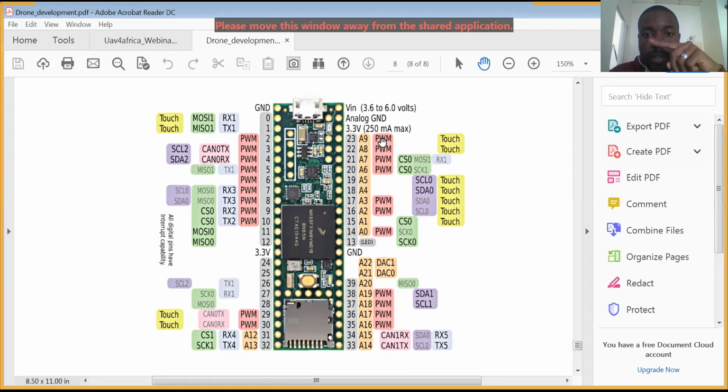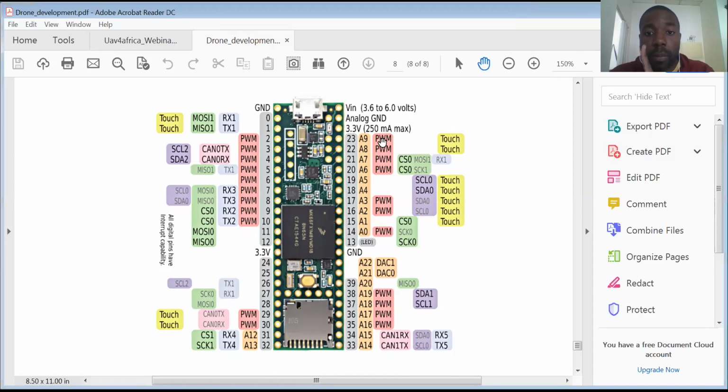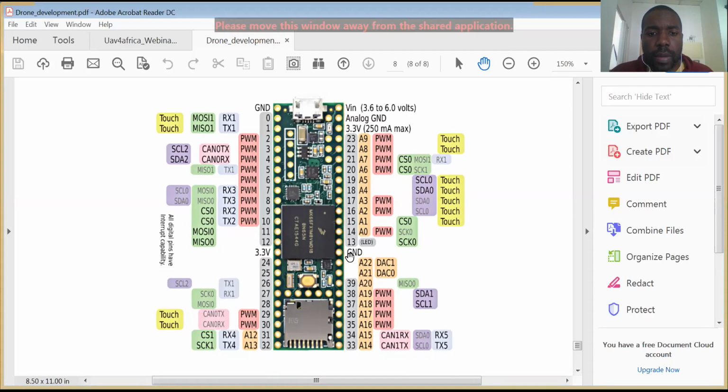Basically, it's pulses on your motor, and the different shapes of pulses cause a different amount of force. And that's really what this does. Without this, you have to keep on adjusting as the pilot. You've got to keep on doing what I just did, change here, and continuously. But if you have something like this, you're able to basically do a command, leave it alone, and the drone will be stable.